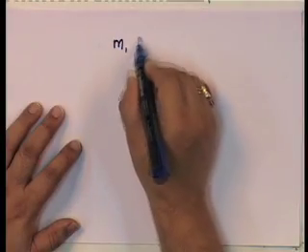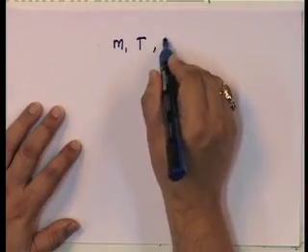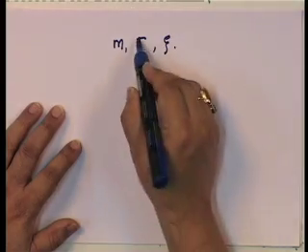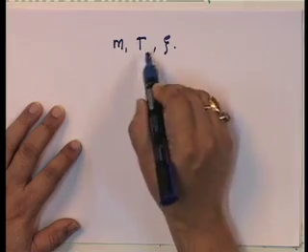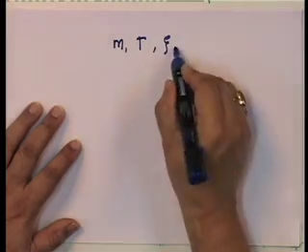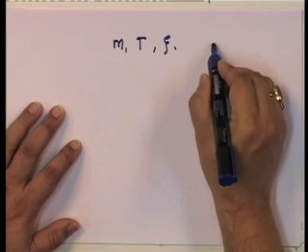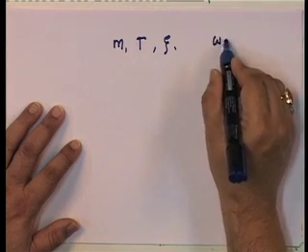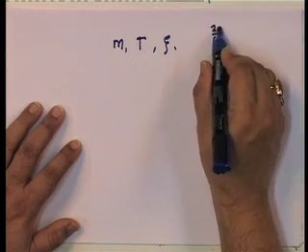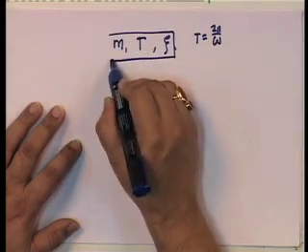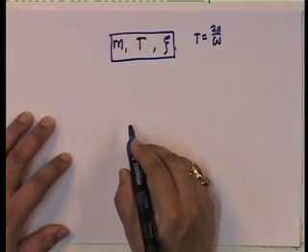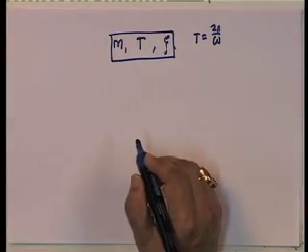So, I am defining a structure by its m, T and psi. These 3 define everything. They define m, k, c, everything. So, this is what I am defining, but T is nothing but the time period. So, this represents the single degree of freedom structure, and let me find out the response to this.